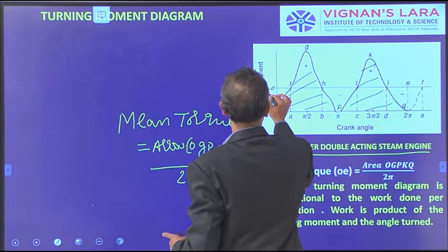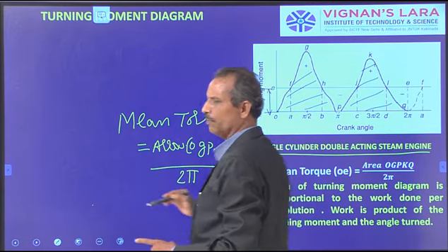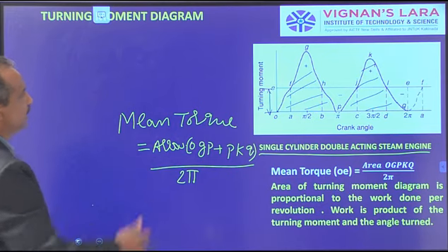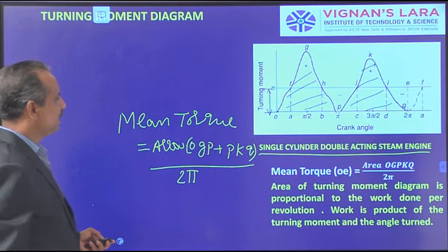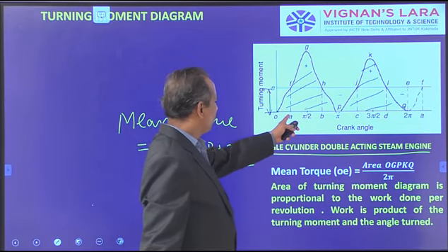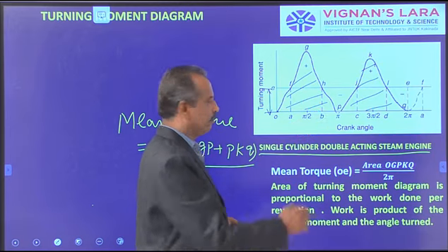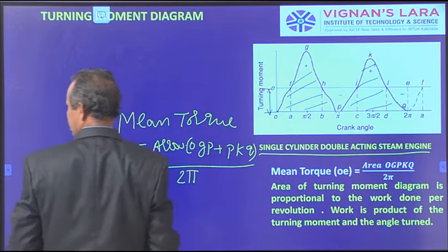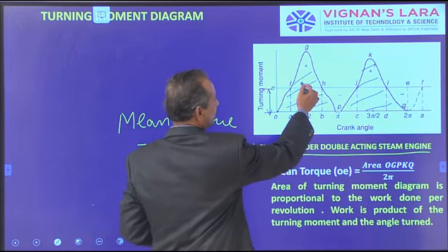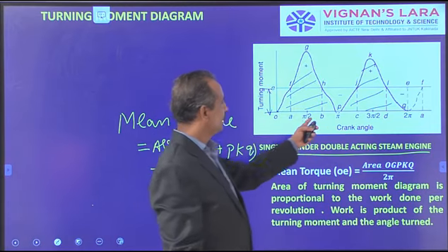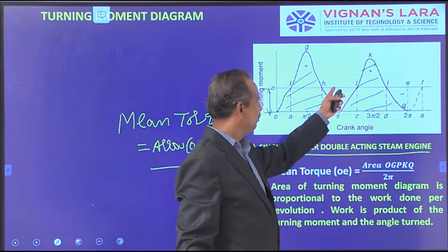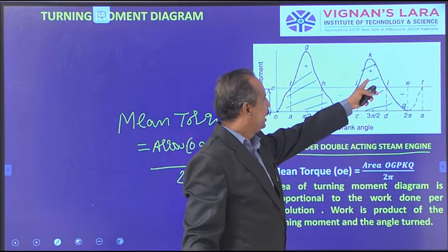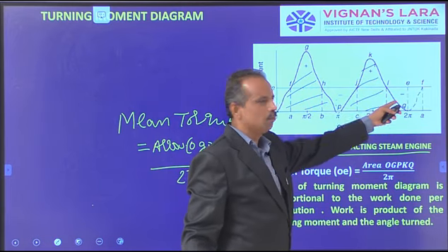So that is the magnitude OE. A constant magnitude of turning moment, if it is applied, gives this. In this case, you can see from A to B, the angle A to B, this flywheel has more energy than it requires, whereas from B to C it has less energy because of a shortage of energy. That is why here it is shown minus and this is plus, and here also it is plus and here it is shown minus.